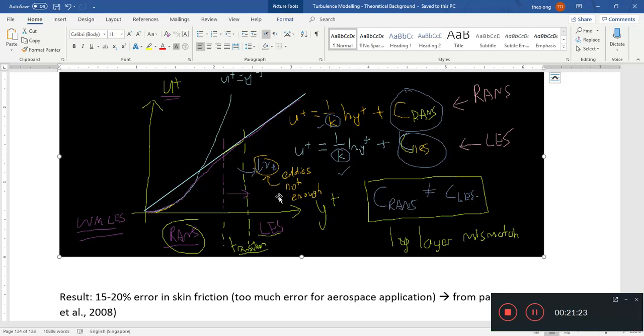The CFD software actually solves for the velocity field and all the eddies. So the eddies which you see in your CFD simulation, which are not part of the turbulent viscosity, these are resolved eddies. These are eddies you can actually see in your simulation, and they are part of your velocity field. So the resolved eddies do not make up for the drop in this nu t.